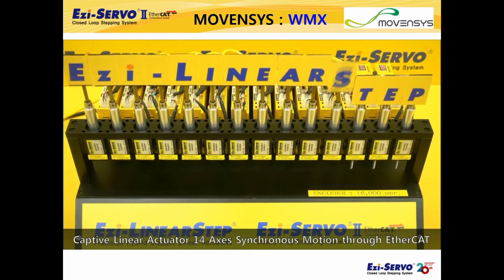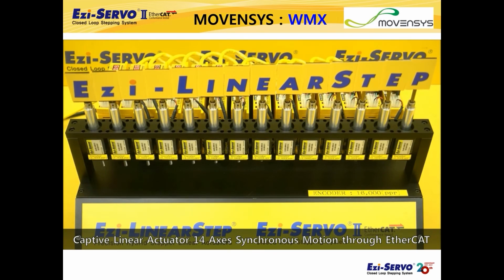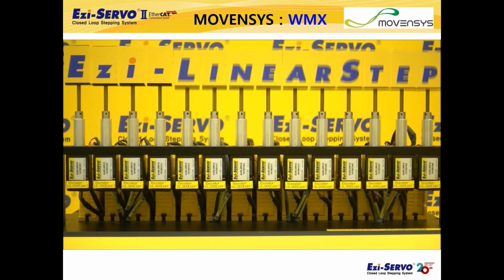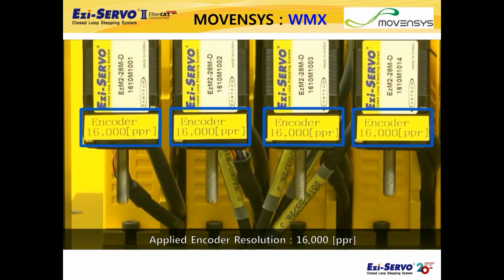Linear Step is a product that combines a motor and a lead screw linear actuator. Linear Step is capable of high-precision position control by attaching a high-resolution encoder to the stepping motor. As you can see, in the demonstration, an encoder of 16,000 ppr resolution was applied to a 28 mm linear step motor.